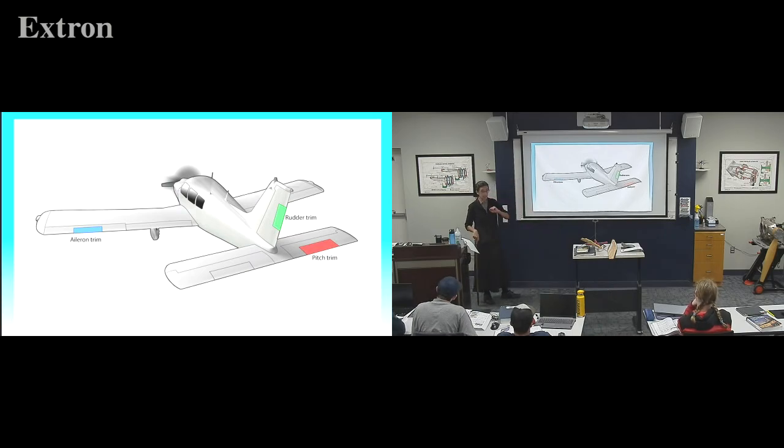On a 182 and a 210 and a 172, if you ever see aileron trim, or they slap on a piece of metal you can bend like the rudder, that airplane is messed up. Because they have the wings somehow not rigged correctly, and they're trying to compensate by slapping on aileron trim. So if you ever go to buy an aircraft, watch for that.